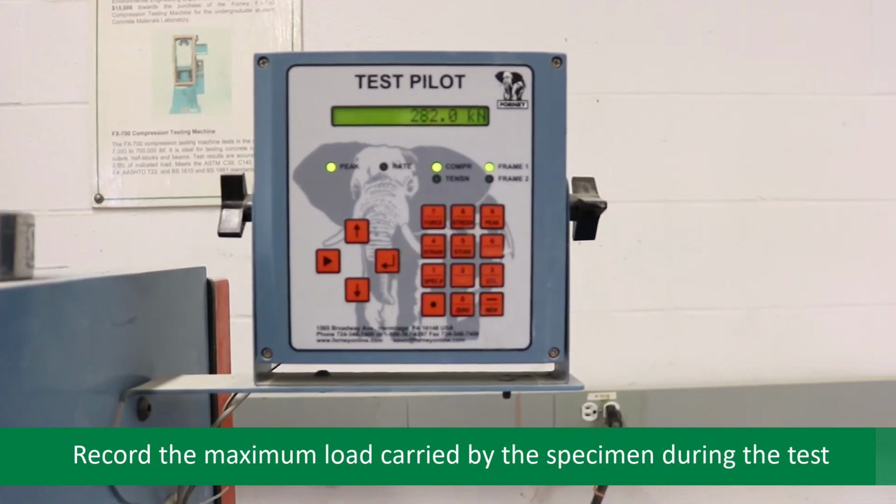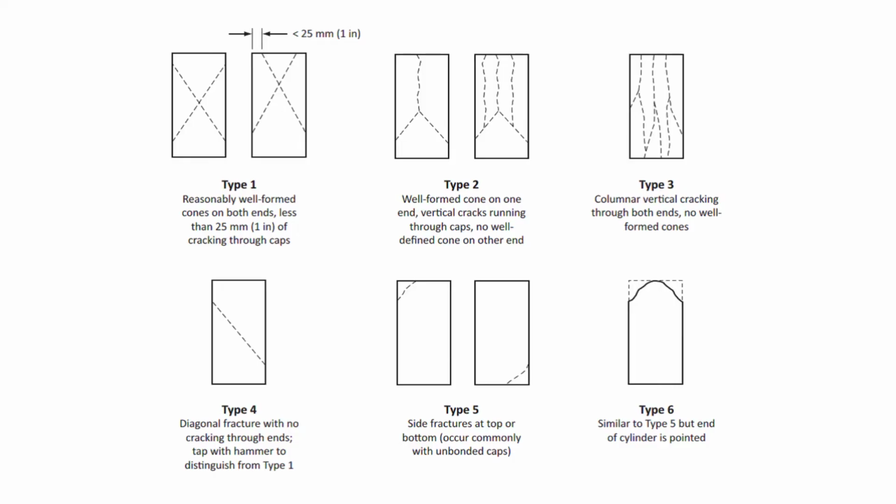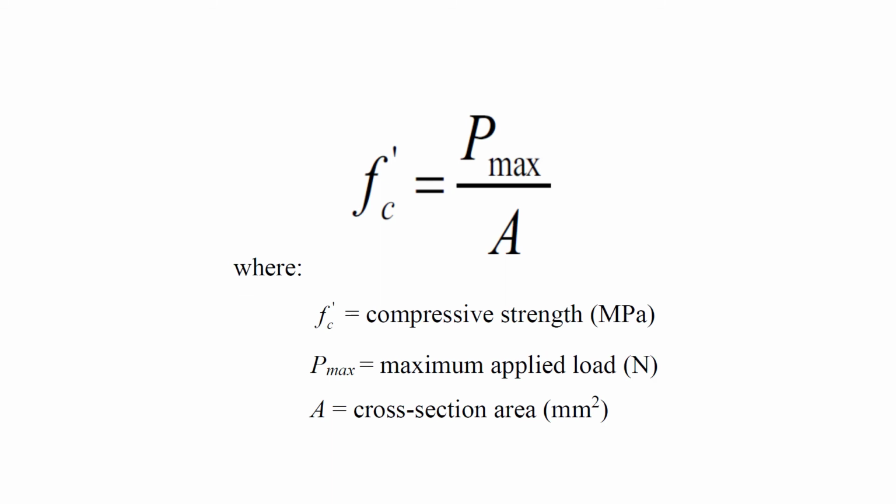Record the maximum load carried by the specimen during the test. Note the type of failure and the appearance of concrete. See Figure 1 in your manual. Finally, calculate the compressive strength. See your manual for the formula.